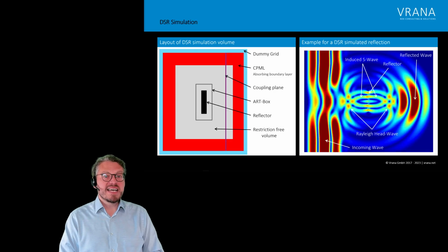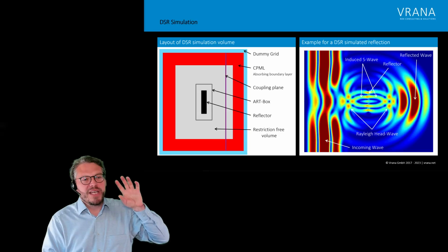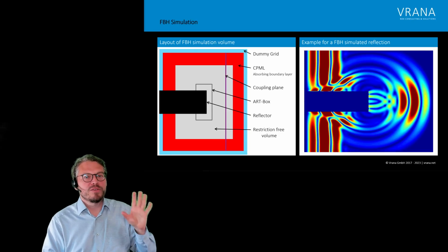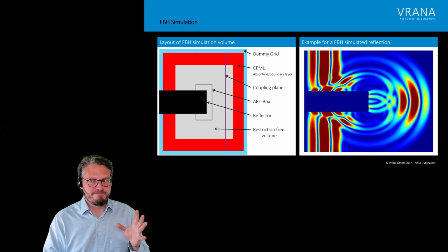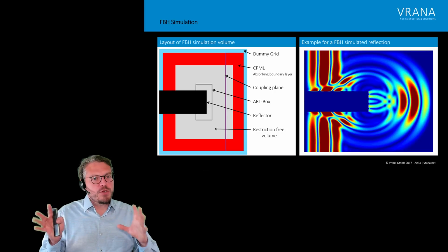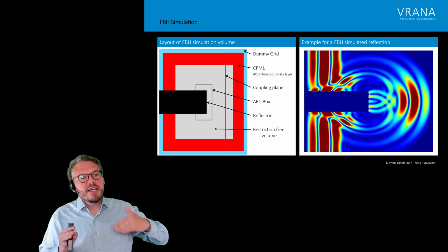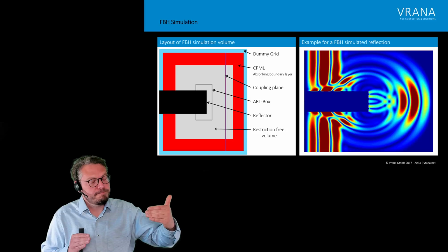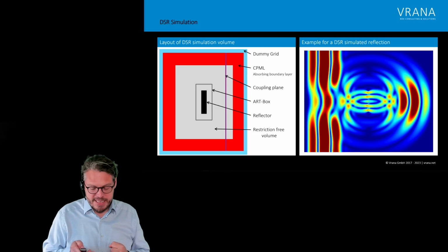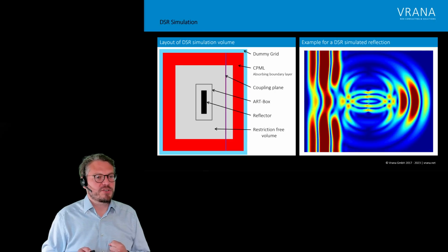Now, what we did here is a disc-shaped reflector. We didn't only do disc-shaped reflectors, we also did flat bottom holes. The situation we had here is that we simulated a pretty big indication, so actually the Kirchhoff approximation is true. But still, we can already see some difference between a flat bottom hole and a disc-shaped reflector.